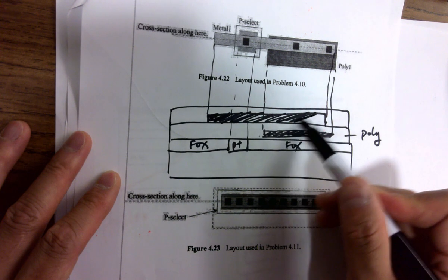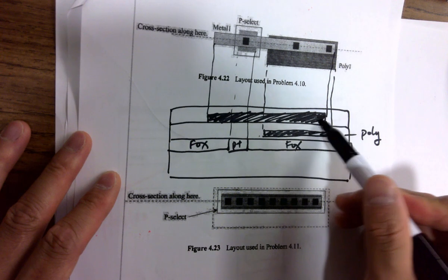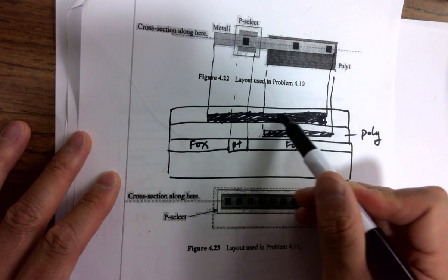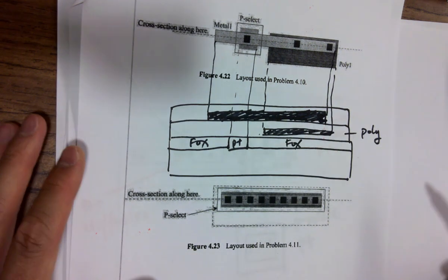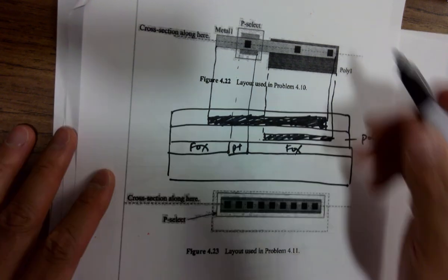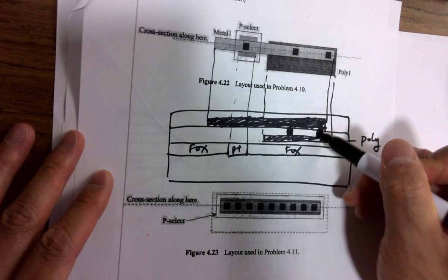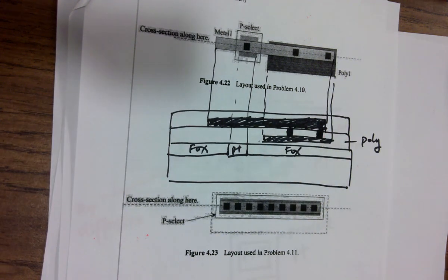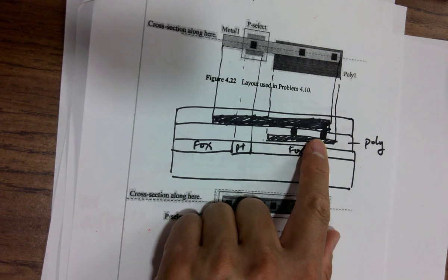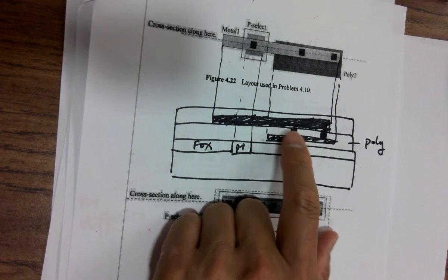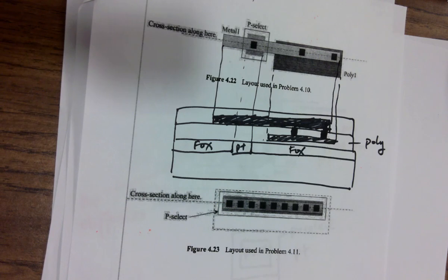And why does metal 1 need to make a contact with the bottom? Why is that? So via can conduct currents with it, right? So you have one via here, another via here. But poly doesn't need to have any direct contact with anything underneath it. But you do need a via above it. And since metal 1 is touching the bottom, it's making things possible. Does that make sense? Yeah.